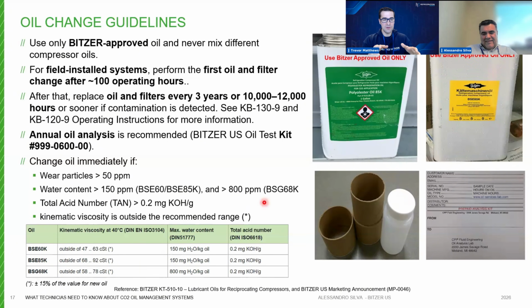Because in my CO2 course I'm teaching the technicians how to read these, and this is exactly what Alessandro is talking about here. When you look at that document and it shows metal in there, that is a problem. That is pieces of the compressor, and you should not have pieces of compressor in the oil. It should be oil, that's it. No water, no air particles, no metal. So this is so important. Exactly, this is our recommendation.